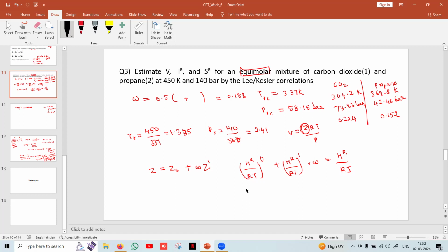then how much may the volume increase? You can't apply the ideal gas assumption for every system, right? For that type of fluid, what type of equation of state is followed, and how much deviation from ideality is there, you should account for that. And if I increase the temperature this much, how much will the volume be? What empty space should I keep for safety purposes?